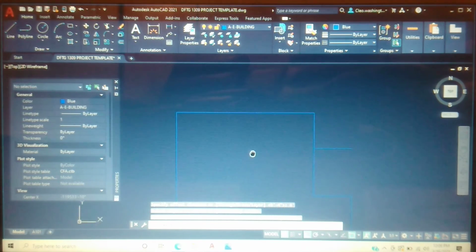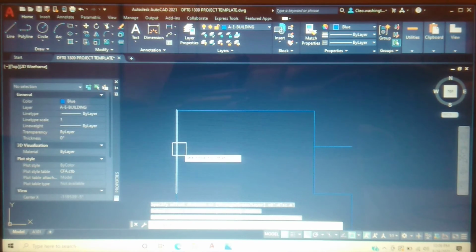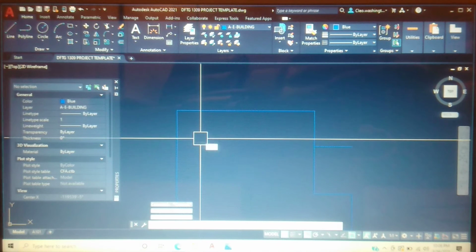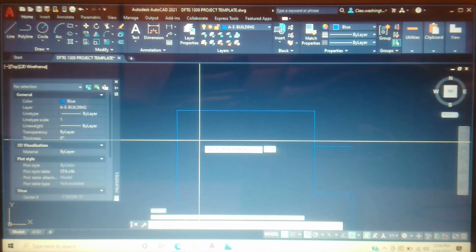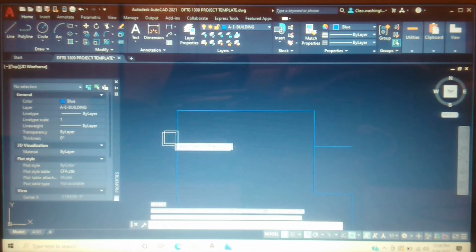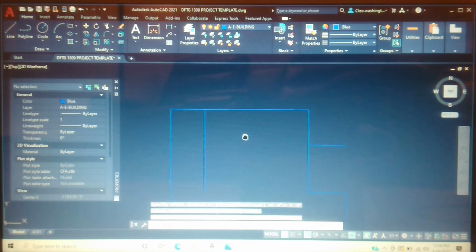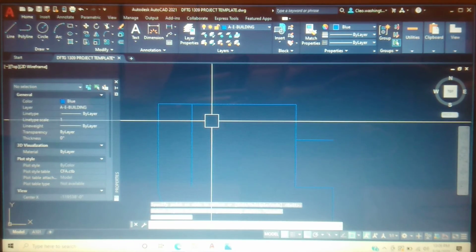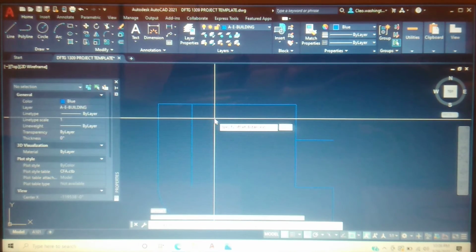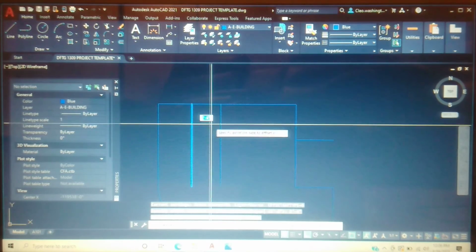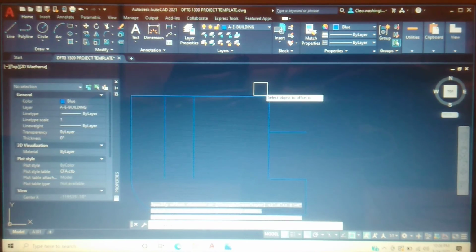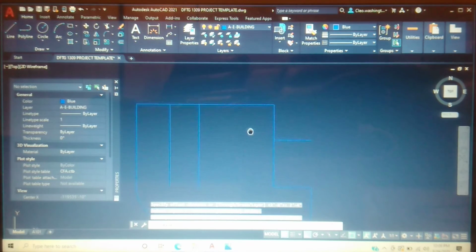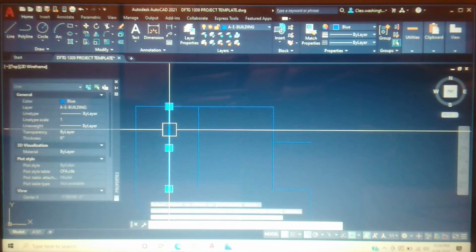And they don't give us the curve here. So what we'll do is we'll take this line, if that's 2'4", let's just say 2'8", offset this line 2'-8". Let's take this line offset at 2'8", something like that. And then offset 2'-4", offset 2'-4". You take this line and boom, just like that. So now there's where you have your angle, okay? And you can actually delete this line.